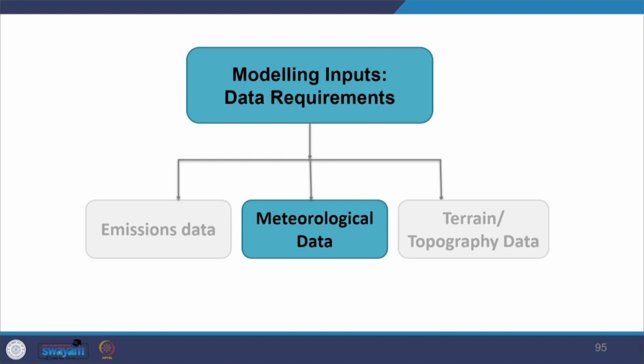It is suggested that, as weather patterns vary from year to year, when modeling is undertaken for large scale industrial installations, one should use 3 or 5 years of meteorological data and should compare the results. Even CPCB gives you these guidelines, you may look into that.